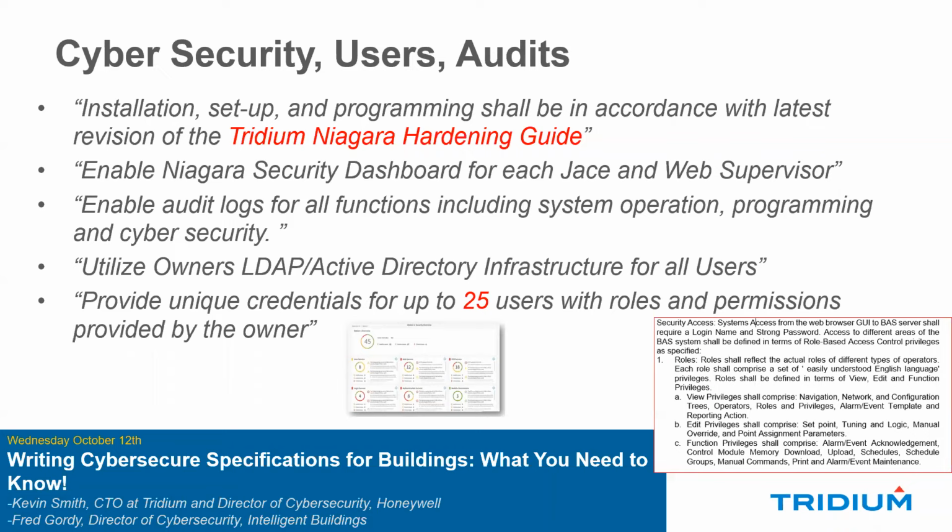Some language might be: provide unique credentials for up to 25 users with roles and permissions provided by the owner. Regardless of whether that's with LDAP or regardless of whether that's built in, you never know how many credentials are going to be needed, but you don't want to have to be at the last minute adding a bunch of credentials as the building's being occupied. So I think these should be done well in advance. And it's incumbent upon the owner to provide you those details of the 25 users and what their roles and their permissions will be.